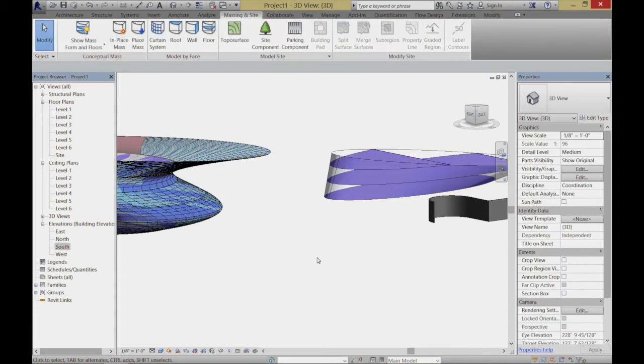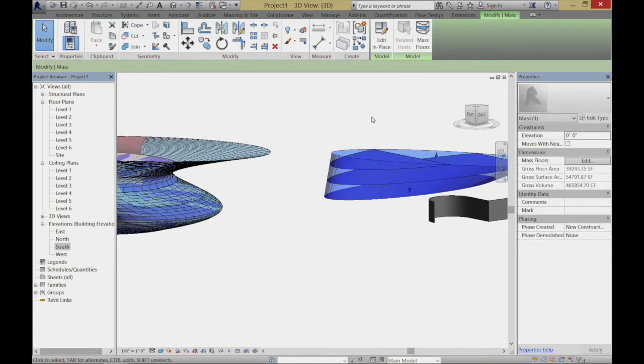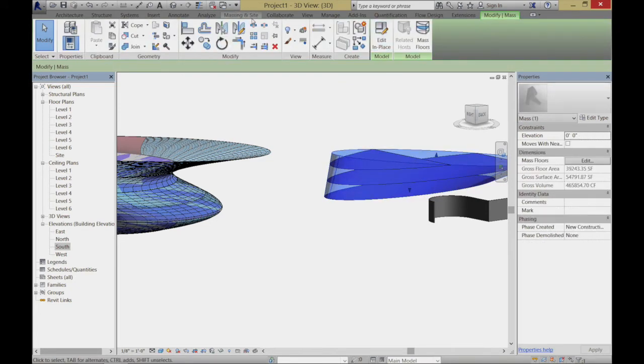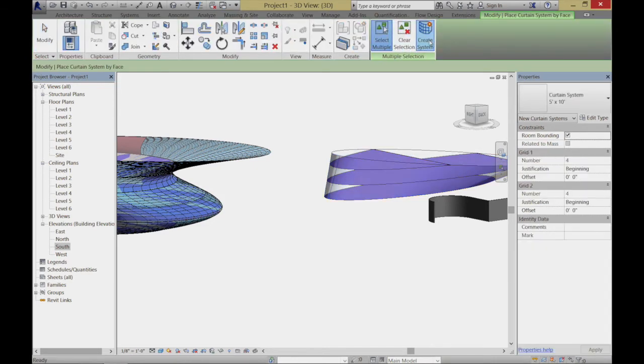Okay. Going through and making this building with this kind of unusually shaped wall, that's easy. We can go through and convert something like this to, for example, the curtain wall. That'd be fine. Massing insight. I'll make the curtain system out of that. If we want to go ahead and have this very simple curtain system, this 5x10 curtain system, which is just these rectangular panels, super, we can do that.